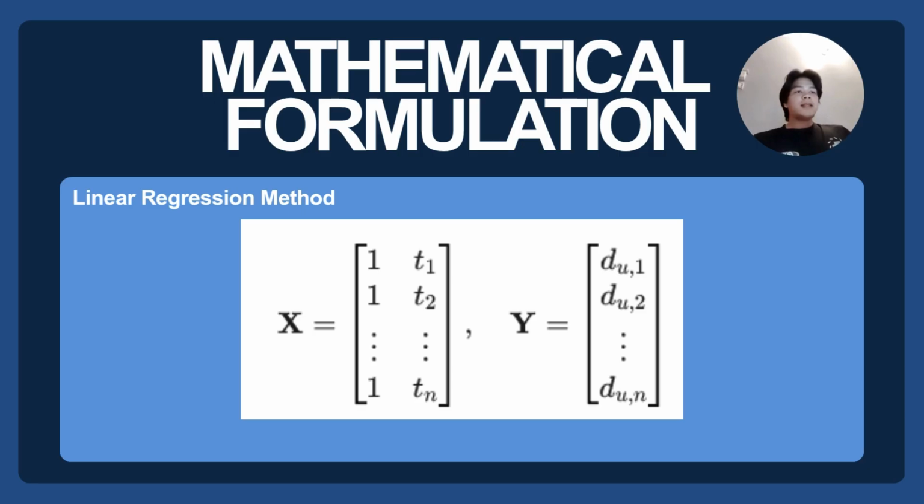The linear regression method is used to map the continuous corrosion depth profile over discrete operational time measurements. A matrix-based least square approach is used. The Vandermonde matrix X and the observation vector Y are constructed from the experimental data pairs.